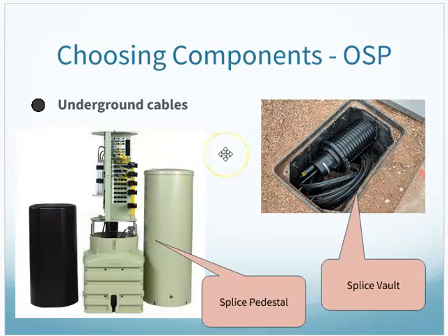And then when I'm done, I need to make sure I have some sort of protection for those splices, whether it be a pedestal above ground where you do the splicing and then cover, or a vault in the ground where your splice is in there and then it's covered up with a utility cover, if you will.